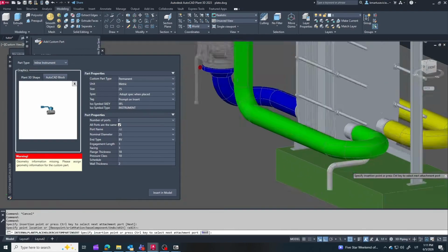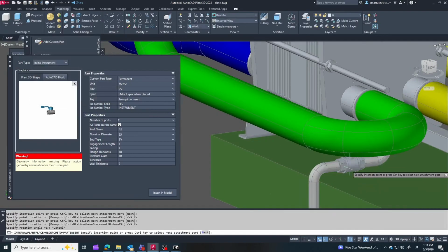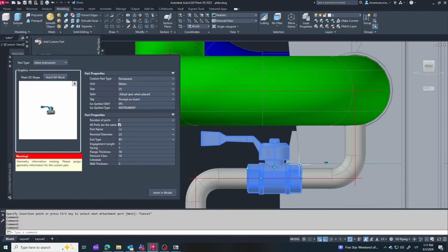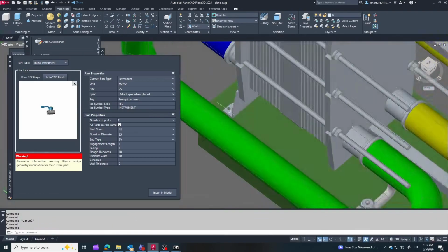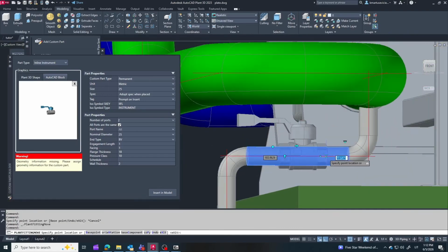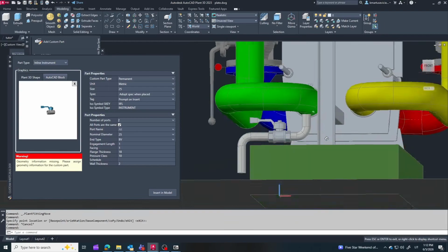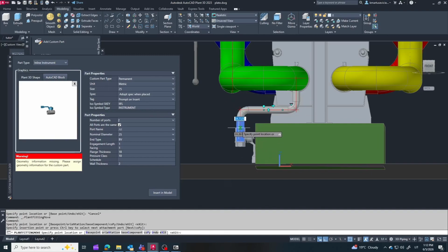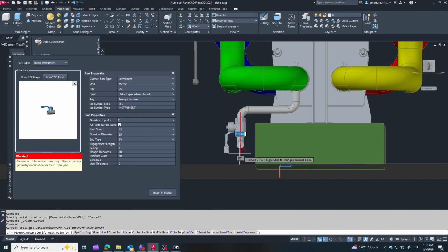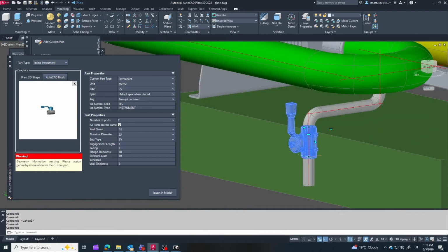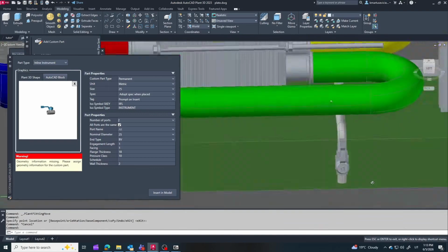Why do we need drains and vents? Well, when you fill the system with water, air gets trapped at the highest points, creating air pockets that block fluid flow and drastically reduce heat transfer efficiency. To fix this, you must place a vent valve at the absolute highest point of your piping run. On the flip side, whenever the plant needs maintenance, a shutdown or winterization, you have to completely empty the system. Fluid can't magically drain uphill, so you must install a drain valve at the absolute lowest point of the line. Skipping these means operators won't be able to safely service the equipment.